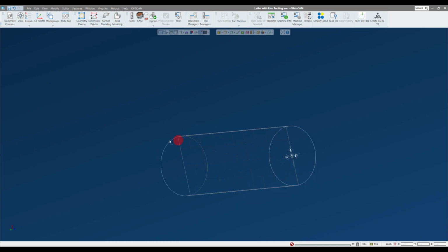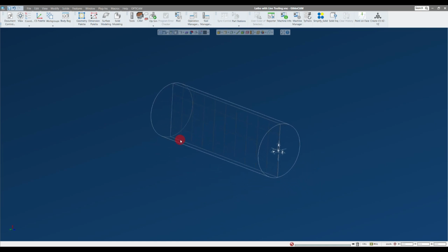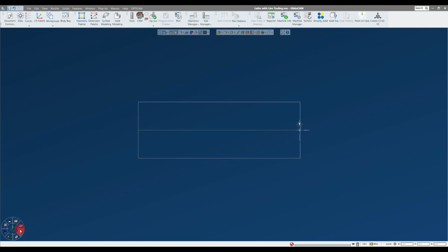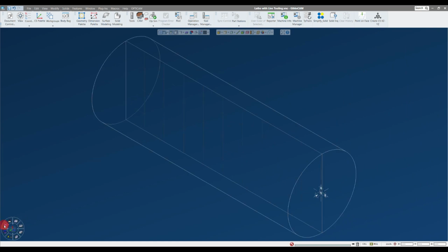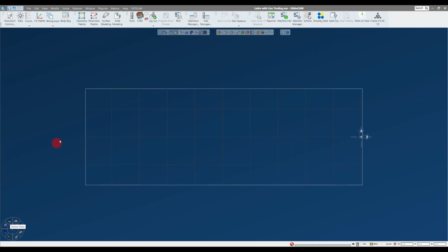Now, you do also have in the lower left corner of the screen this small coordinate system indicator. And if I just move over it, I have all of these viewport icons. So I can go top, left, right side, and isometric view. If I should happen to get my object off the screen, I can just hit this magnifying glass here and unzoom and bring everything back centered. And then my home view is going to give me a normal or perpendicular view to the actual coordinate system, which is this grid that you see on the screen.